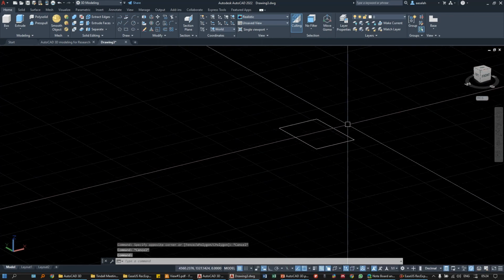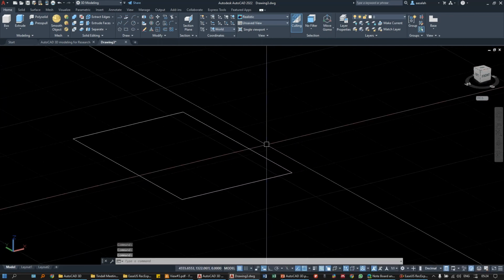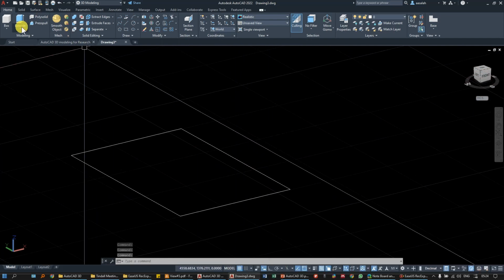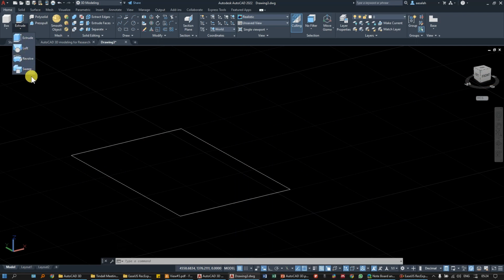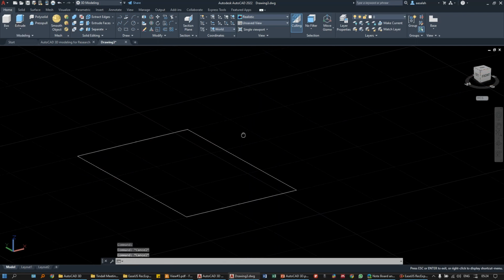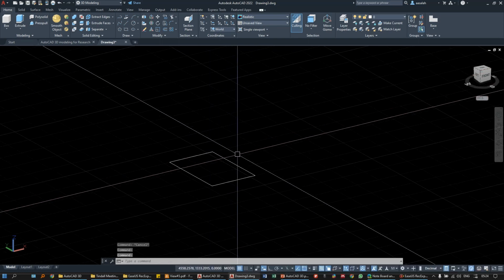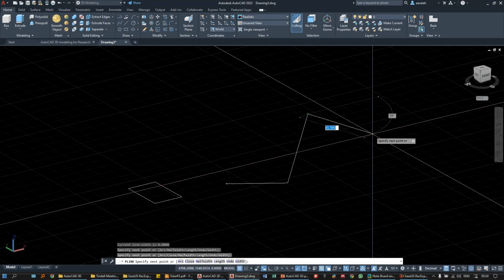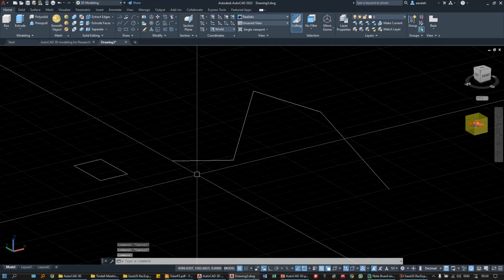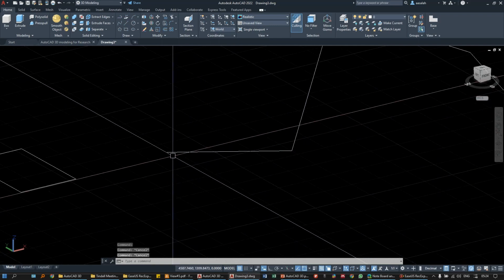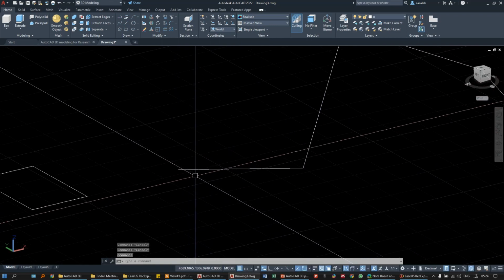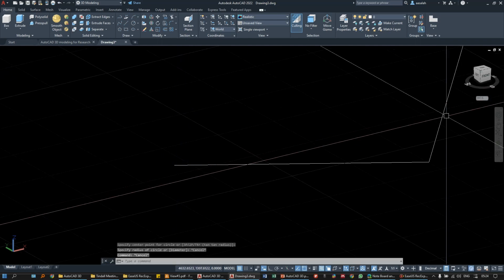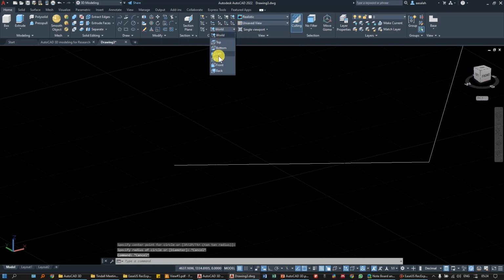One more thing I want to explain here is how to create reinforcement and how to use polylines in order to create, for example, a bar that we need to extrude. For example, this one, let me draw this polyline. Let's say we have this polyline, and I want to extrude it into a rod or even a square section or whatever. I'm going to draw a circle on this one, but let's look at the left face.